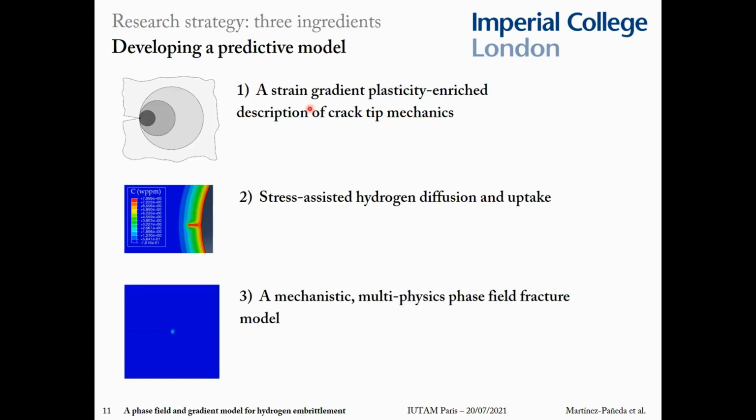And I think that in every problem that you look at, of course, you always need to think of what are the critical variables of your problem. In this case, stresses, crack tip stresses, and hydrogen concentration. And also, what is the critical distance? And in this case, the critical distance for fracture is a few microns ahead of your crack tip, so very close to the crack tip.